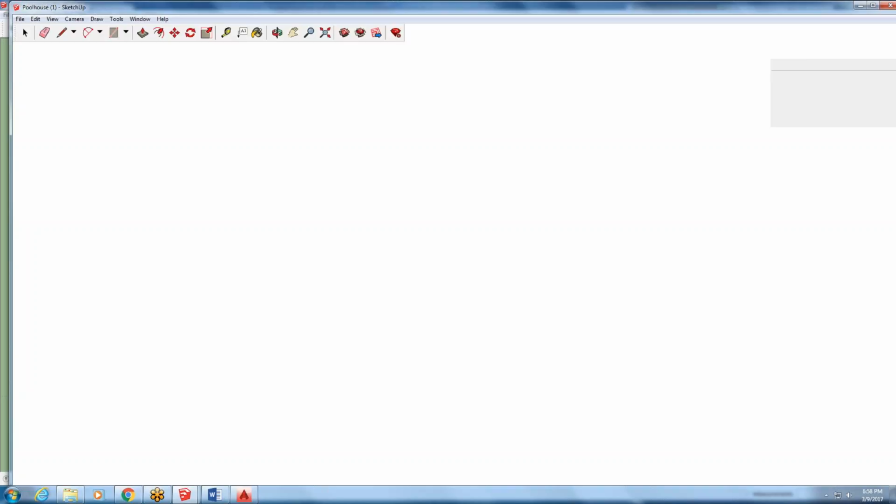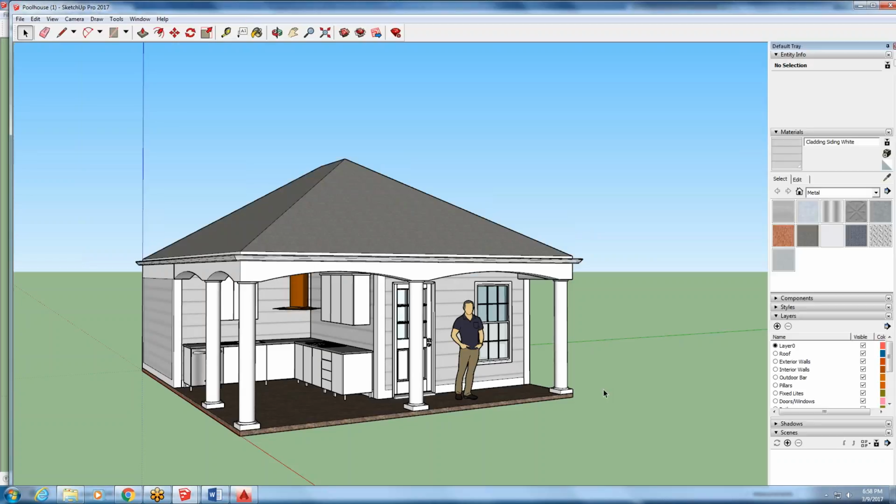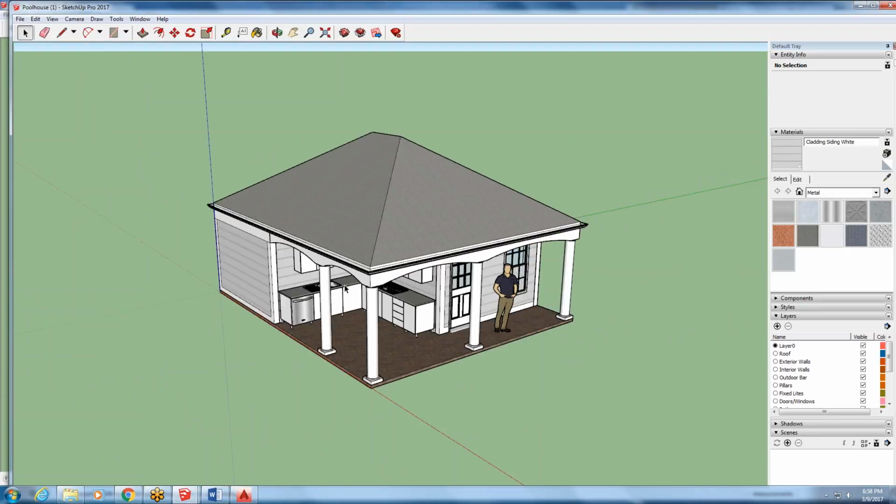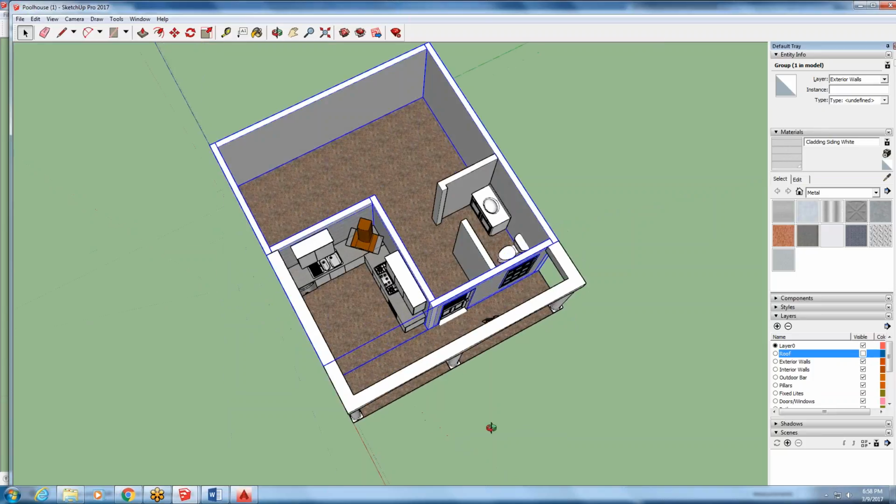So here's the exterior office that we're going to be drawing in this class, and then you're going to be filling in all the furniture and some of the space planning on the interior of it. Notice that I have all of these layers, exterior walls, interior walls, but then here's east wall, west wall, south, and north. These are the ones you're creating this week, and slab. There'll be other ones we'll create later. If I turn my roof off, and notice visibility is like AutoCAD, so I have a roof layer, and if I uncheck the roof, now I don't see the roof, which is nice.